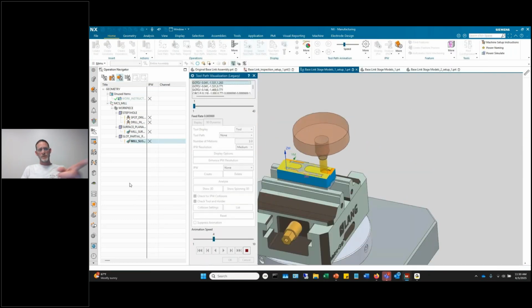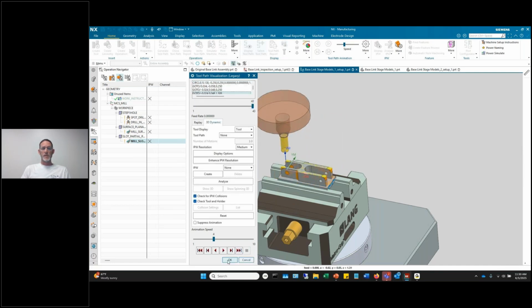That's okay. I just go in there and change it. I go in and change my toolpath and my operations that it gives me, save the tools to the library, save the operation to the database, and then it's as simple as right click, make new suggestion, and then it will give me different levels of suggestions, priority numbers. You can set it from 999 to 1. Every time it sees a 1, it's going to choose it first. If for whatever reason the material properties are a little different than the last time, we can go 80%, choose variant 2. We can get very intelligent with it.